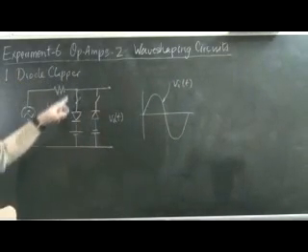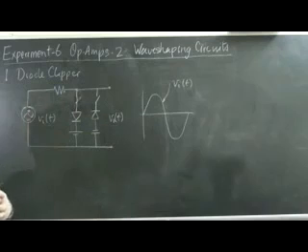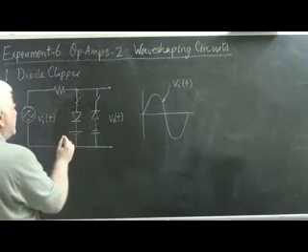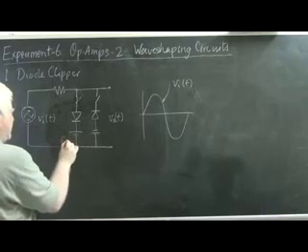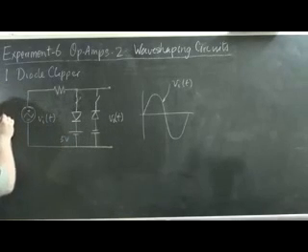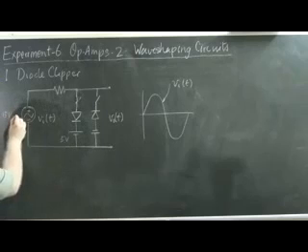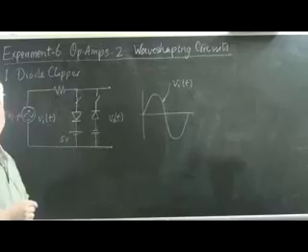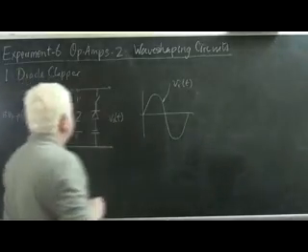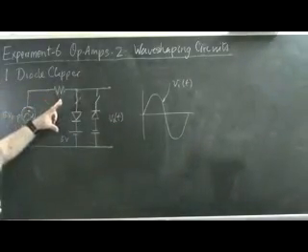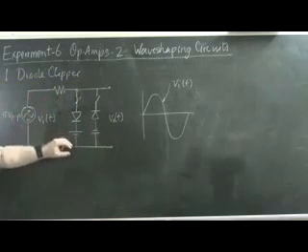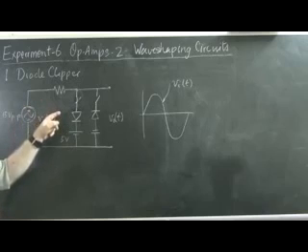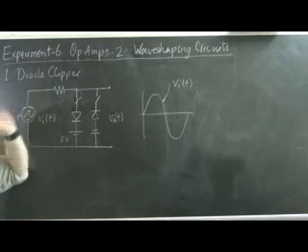When this is applied across this diode circuit and this battery voltage is set to something like say 5 volts, given that this is say 15 volts peak to peak, let's see what happens. As long as the voltage that's appearing here is lower than the battery voltage, let's say 2 volts or 3 volts, 4 volts, this diode will remain an open circuit.